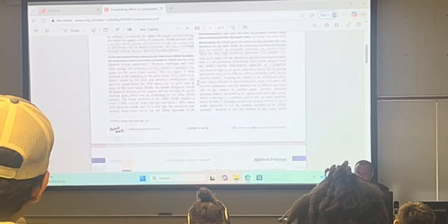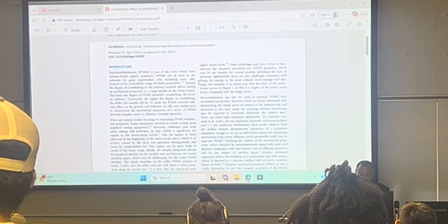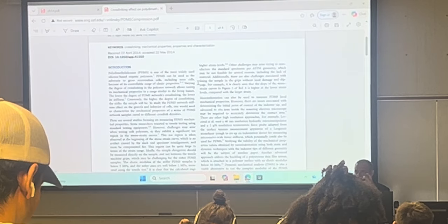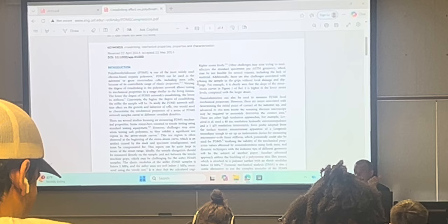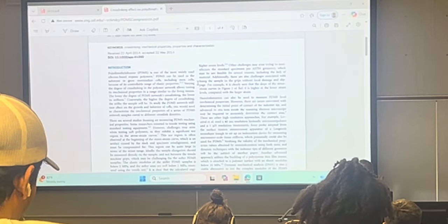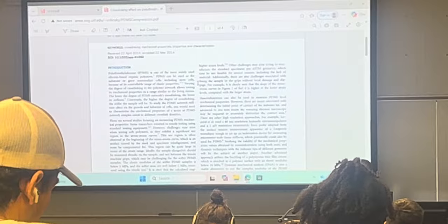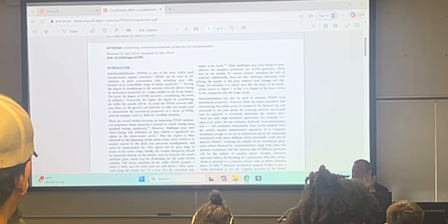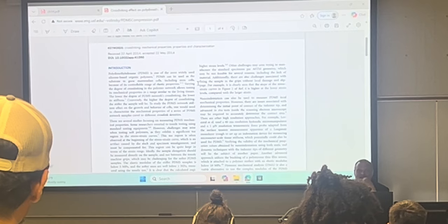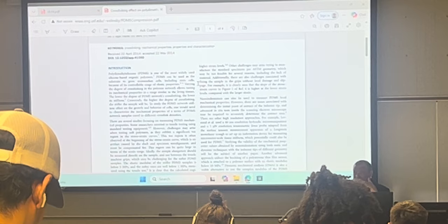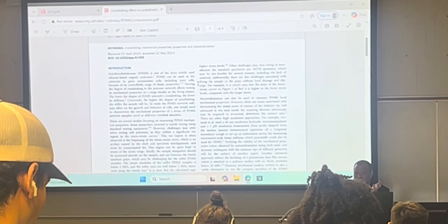And depending on the ratio of the filler versus the binder, you can have different properties. This is why when you go to Home Depot or Lowe's, one tube is $10 and the other tube is $2. But one is rated for some chemical applications, has a warranty of 10 years. It's UV resistant, and the $2 is not.